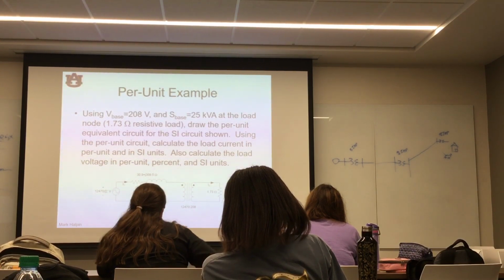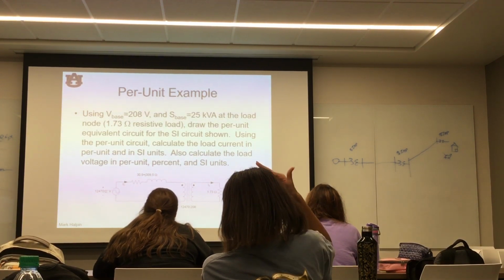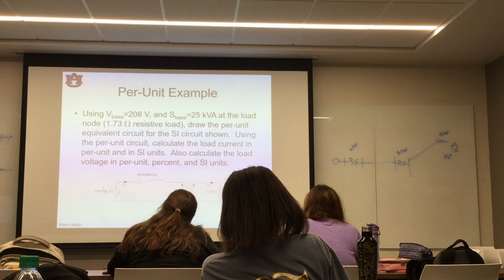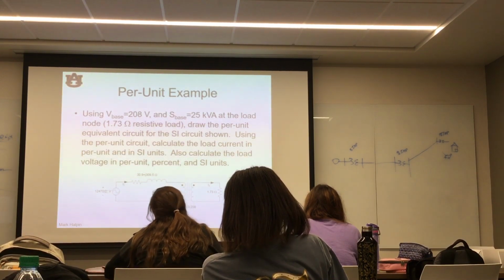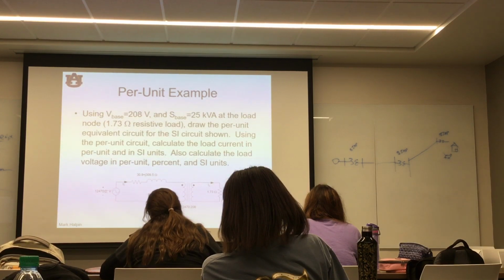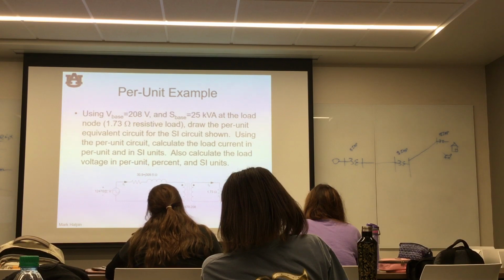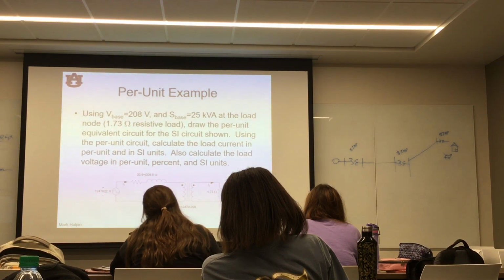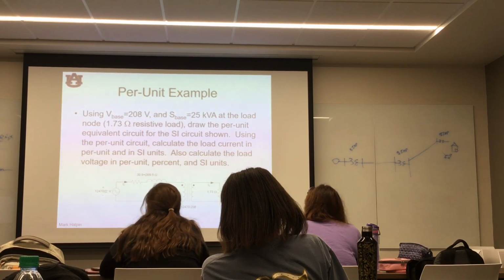So think about that a minute. That transformer over there feeding the house, that's one house. That's going to be a relatively small transformer. That GSU has got to handle all of the power for that generator, and the generator, quite obviously, can power lots and lots of houses. The power rating of that GSU is much, much greater than the power rating of that transformer outside of the house.